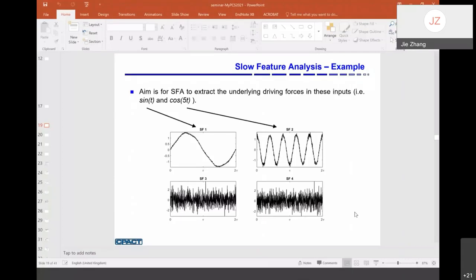But in some cases you may want to retrain your neural network online, for example, if there is process operational drift, so you want to adaptively train your neural network model. In that case, there are other approaches like the extreme learning machine. That one can be trained very quickly, because in an extreme learning machine you don't train the input layer weights. You just take random values as your input layer weights and only train the output layer weights. That can be done in one step, using a regression type approach.